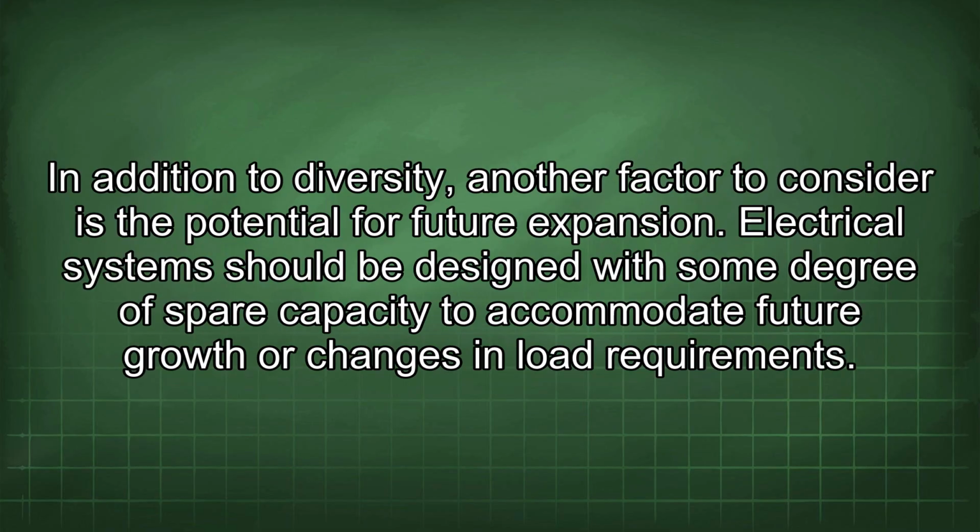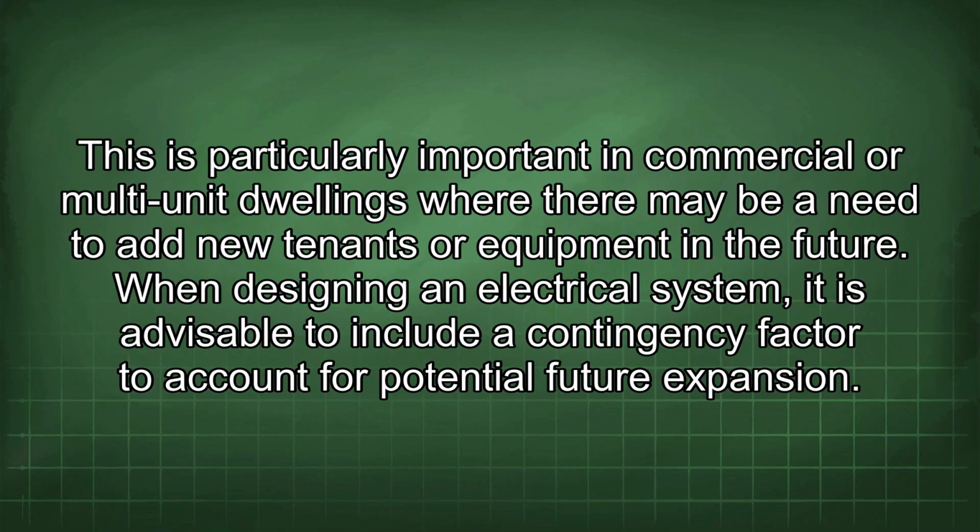In addition to diversity, another factor to consider is the potential for future expansion. Electrical systems should be designed with some degree of spare capacity to accommodate future growth or changes in load requirements. This is particularly important in commercial or multi-unit dwellings where there may be a need to add new tenants or equipment in the future. When designing an electrical system, it is advisable to include a contingency factor to account for potential future expansion.